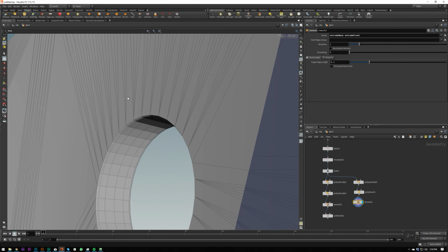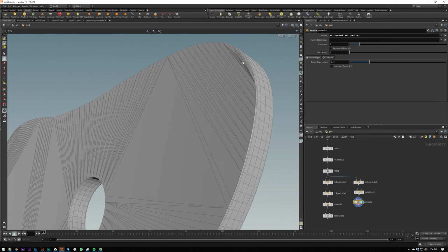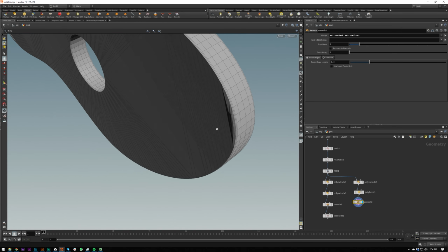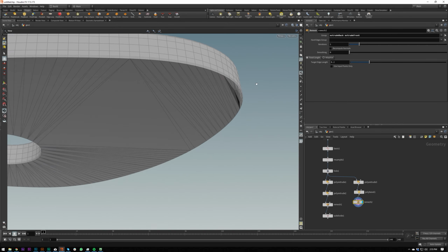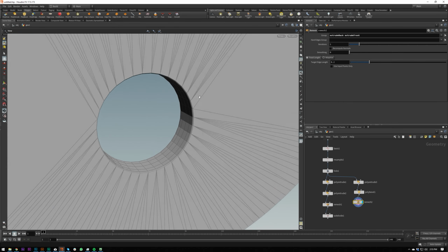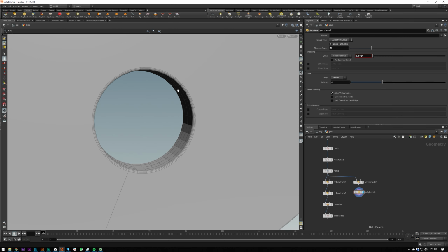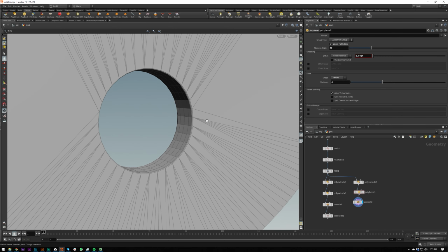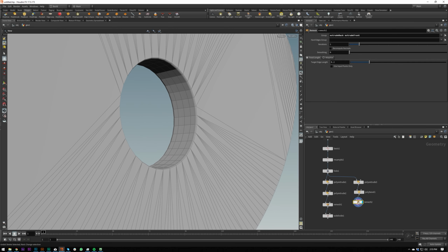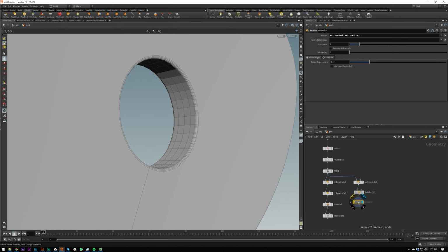At first glance, it's fine, but it's actually connecting to lower down points because we've actually added geometry after we've created these groups. So if I delete that, you'll see we've actually got more geometry there that we've just written over. See that? And we don't want that.